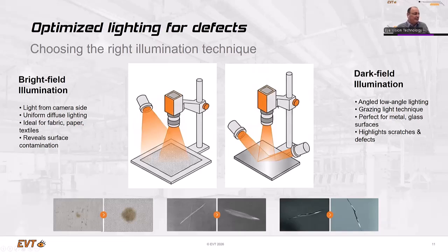And this is sometimes, of course, tricky to organize for an area. If you have a line scan camera, we only have to organize this defect inspection, or this optimization of the light, only for the area where the line of the line scan camera looks.